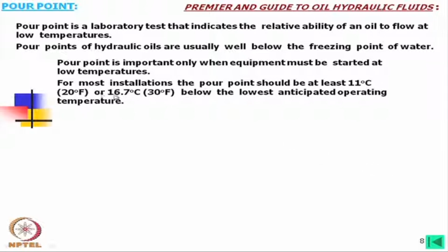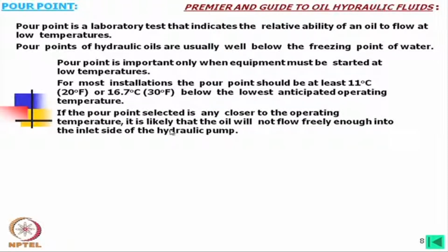I mean, it might be a range, usually from 20 degree Fahrenheit to 30 degree Fahrenheit. If the pour point selected is any closer to the operating temperature, it is likely that the oil will not flow freely enough into the inlet side of the hydraulic pump.